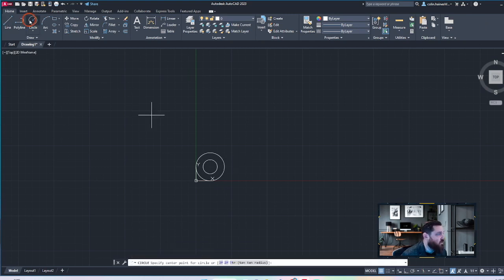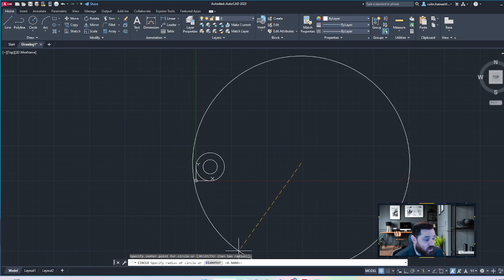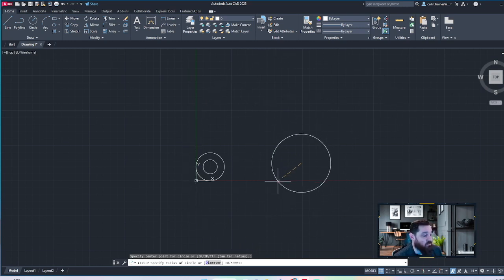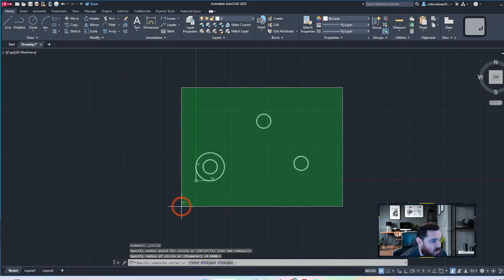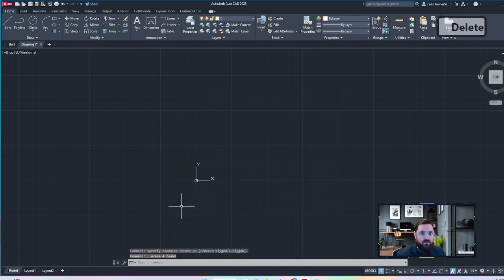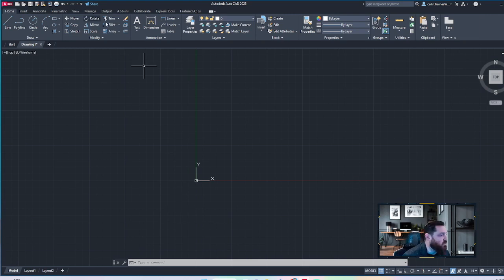or a half. So we'll grab our circle tool again, and you'll notice that still by default, it is set to radius. So you are going to have to manually type in every time. But it does default to the last radius you selected. So if I just hit the enter key, it'll give me that radius of 0.5 every time. So if you are making, let's say a honeycomb or something, which you wouldn't use this for that, the array tool is better. But at any rate, if you want to make multiple circles that are of the same size, that is a good way to do it.